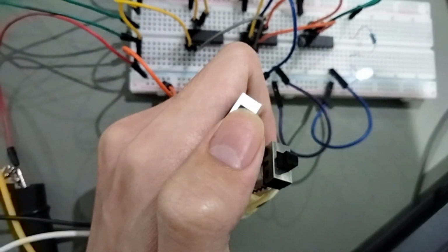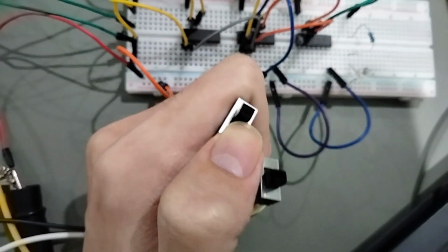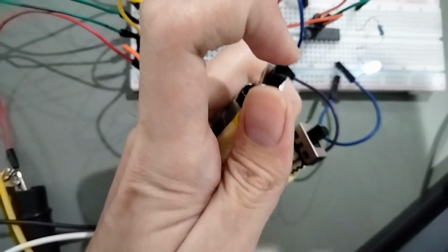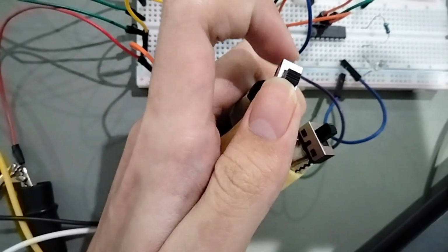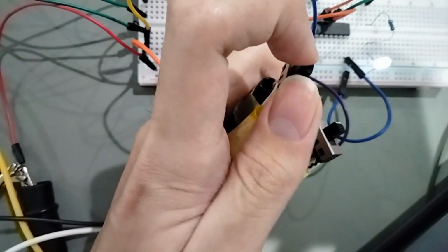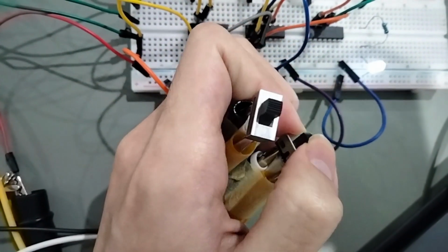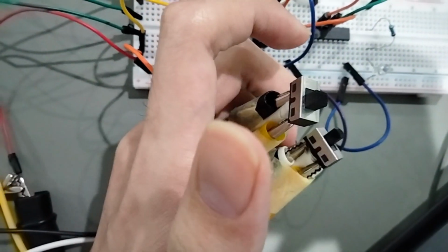Currently, when they are both 0, the output will be 1 since they are the same. When I switch it to 1, 0, it will become 0, and so will 0, 1. And when I switch it to 1, 1, it will become 1. So as long as they are the same, they'll become 1, and when they are different, they'll become 0.